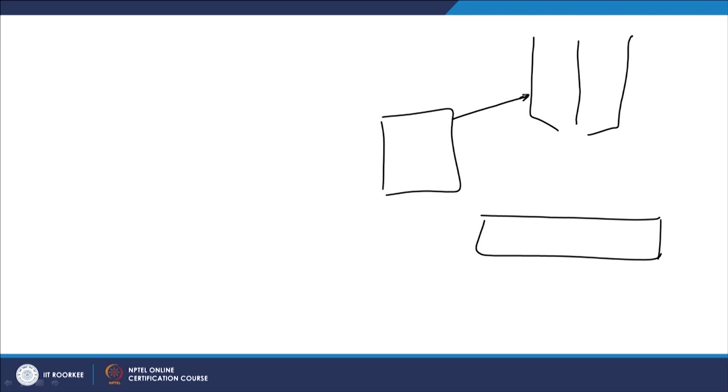In the case when the workpiece is independent of the power source, like this, the electrode is connected to the negative terminal and the positive terminal is connected to the nozzle, the arc is established and then plasma forming gas is passed, and thereafter plasma is forced to pass through the nozzle, then plasma will be impinging with the surface of the substrate. This is the case when the workpiece is not part of the electric circuit.